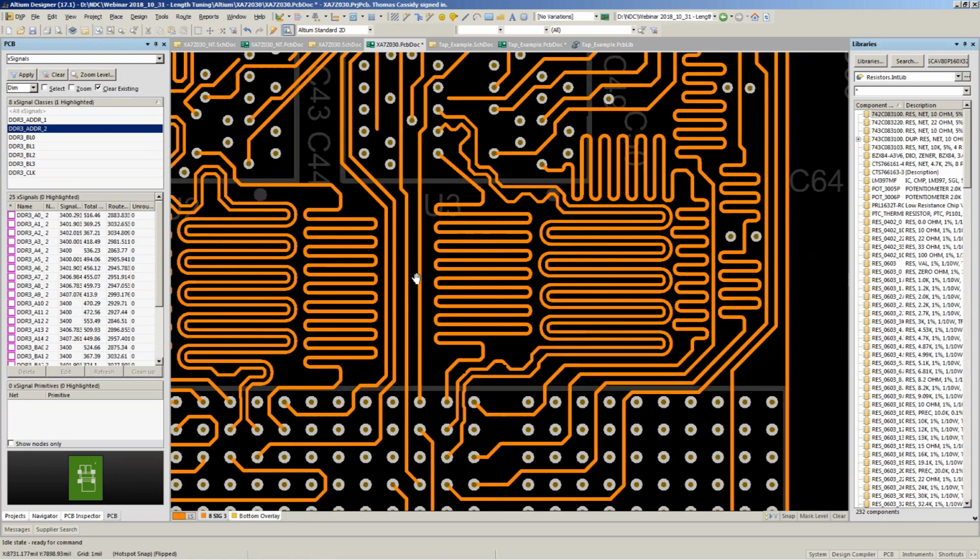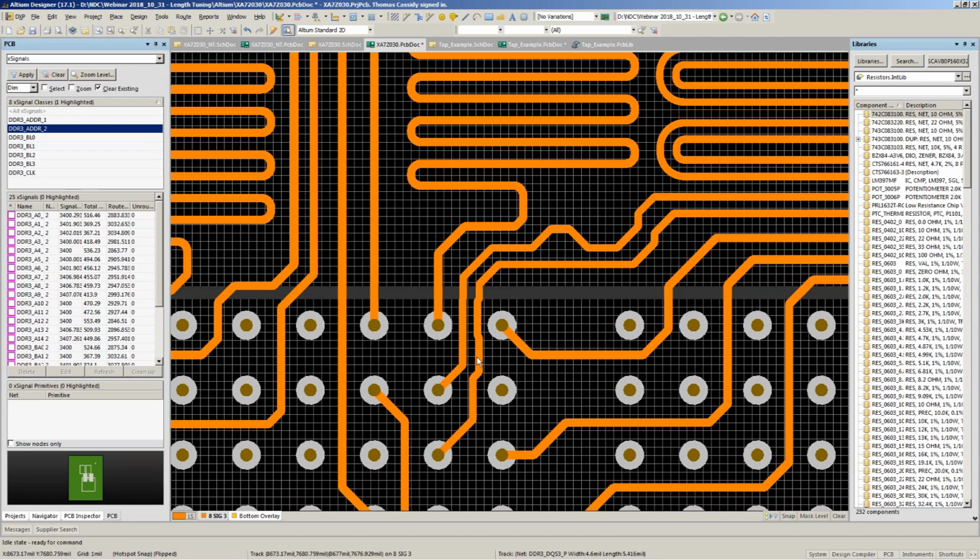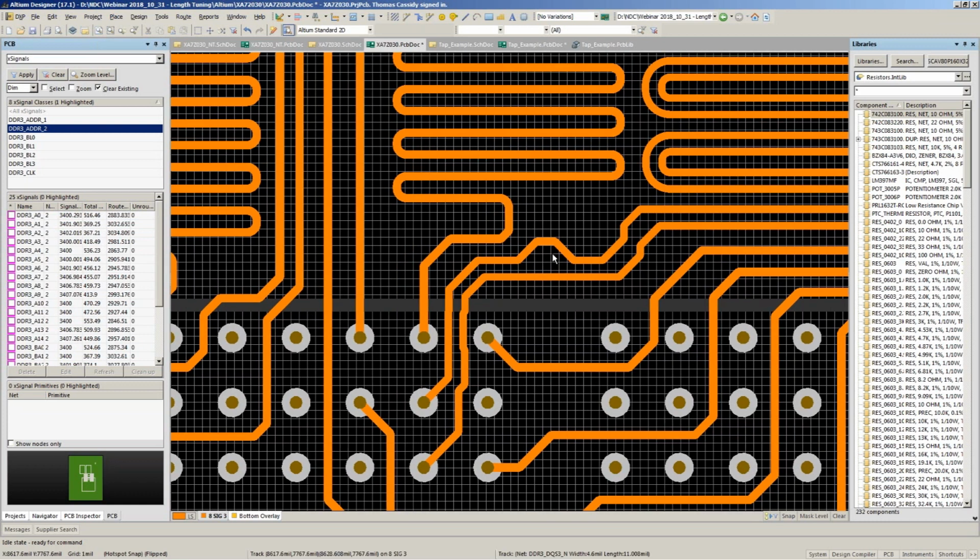I think there was an example up here that Paul liked. Here's a differential pair coming off of two pins, and you can see it doesn't get balanced again until here. This was as soon as I was able to introduce the length tuning between the pairs. And this is a little far. You typically don't want this much space, but once again, you've got to do what you've got to do.